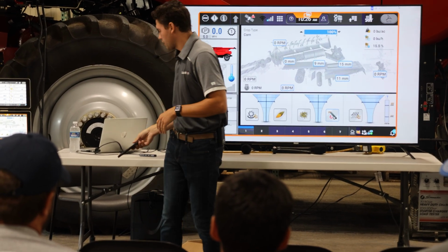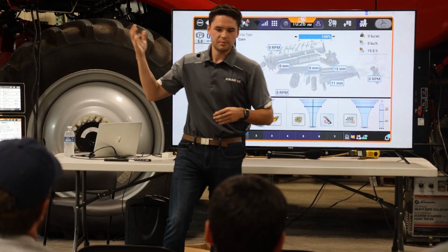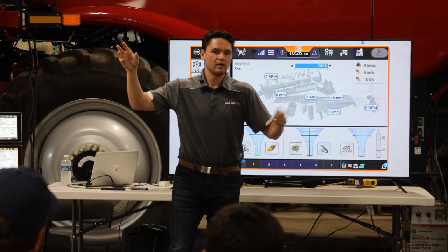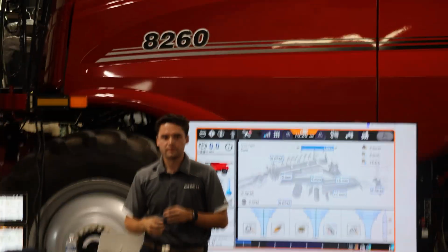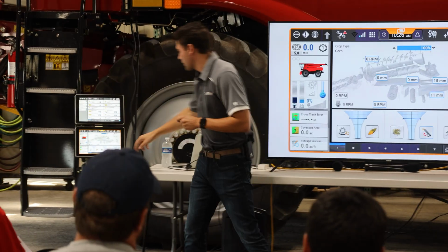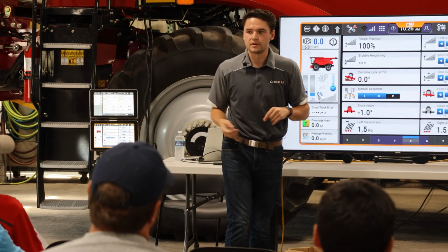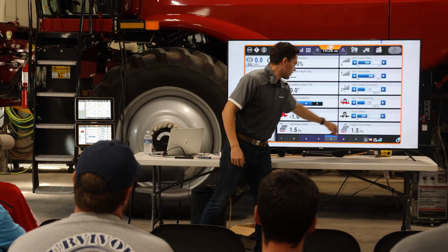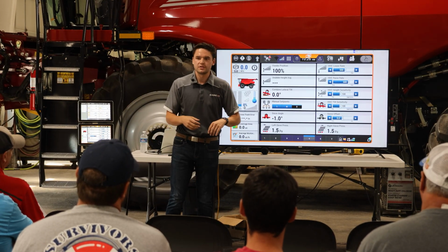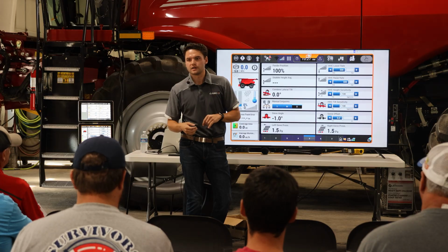So let's say in this scenario we're going through, and on the right side we see a pressure differential. It displays in Pascal. 10 Pascal on the right side and 3 Pascal on the left side. What would that be a good indicator of? Right side heavy. So if you're wondering how do we see that, run screen 5 comes on our 1200s. You can add it to a run screen on the Pro 700, but we have our indicator right here. So the whole thing, how it's determining our sieve load, is just simply through pressure differential above and below the upper sieve, on the right and the left side on the tail end just before our loss sensor.